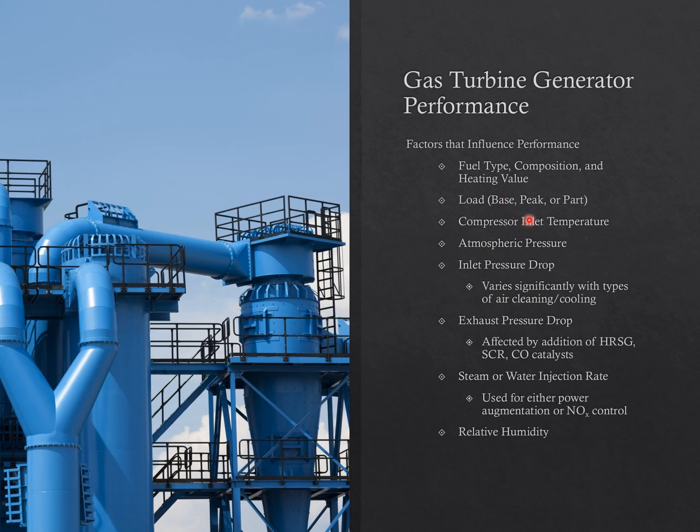Load, that's your base, your peak, and your part. Your compressor inlet temperature, your atmospheric pressure, that's your air pressure, your inlet pressure drop, which depends significantly on the type of your air cleaning or air cooling. Pressure is nothing but the force of that air in a particular area in the system, meaning how much air is pressing into the system. So that's what we want to know.